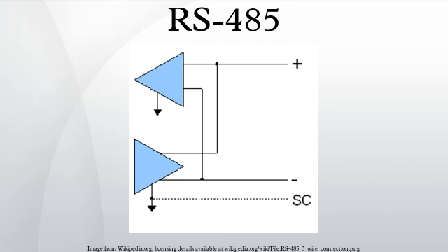This way, the lines will be biased to known voltages and nodes will not interpret the noise from undriven lines as actual data. Without biasing resistors, the data lines float in such a way that electrical noise sensitivity is greatest when all device stations are silent or unpowered.